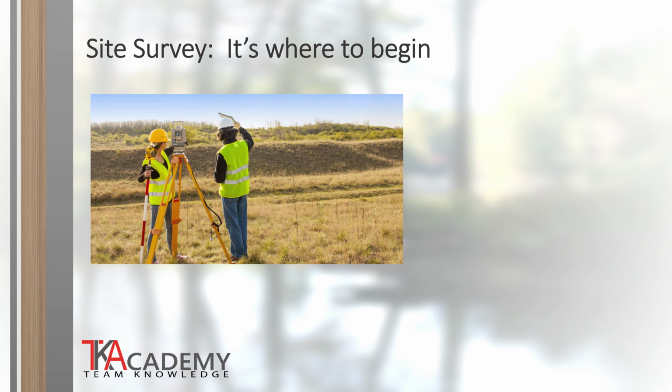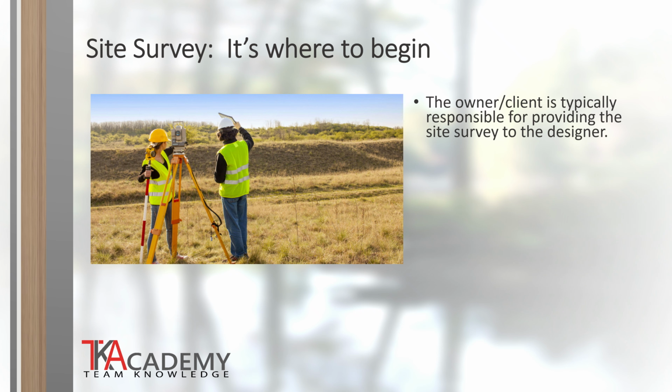Every site design project should begin the same way, by conducting a site survey and gathering information about the existing site conditions. It is the property owner who is responsible for providing relevant and reliable information regarding the site to the design team. Therefore, it is usually the owner or client who hires a professional land surveyor to survey the site and provide the documentation to the design team. It should be noted that in most cases, professional liability insurance for architects and designers does not extend coverage to having the site survey done under its services, even as a subcontract.